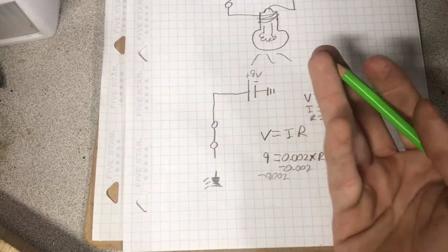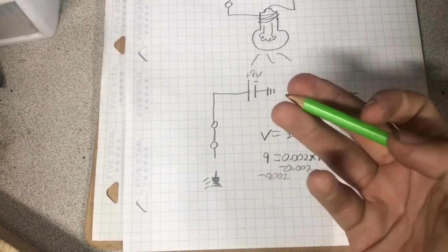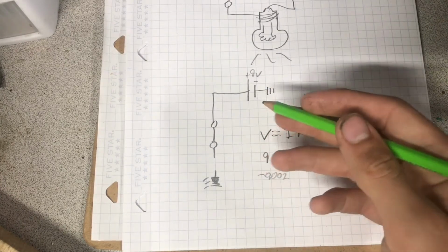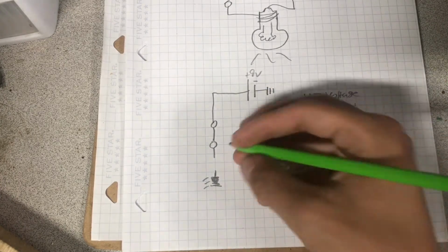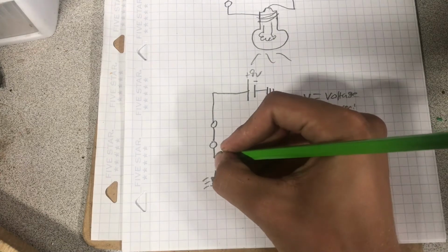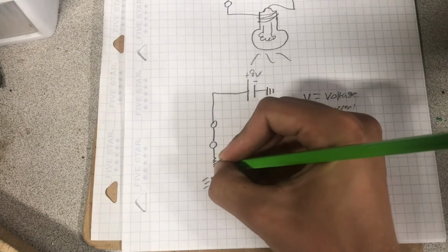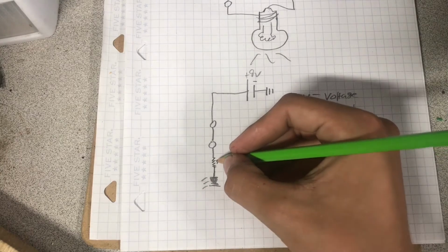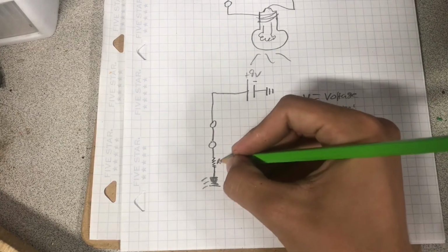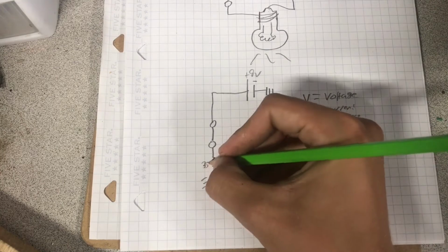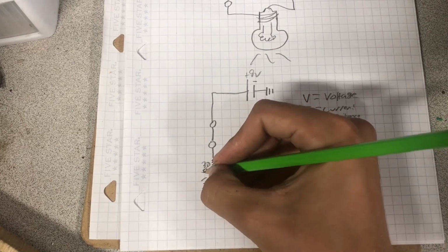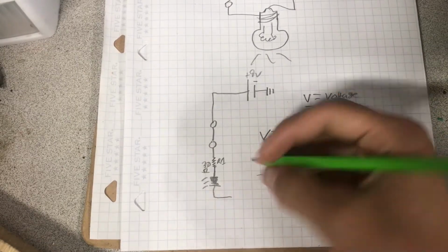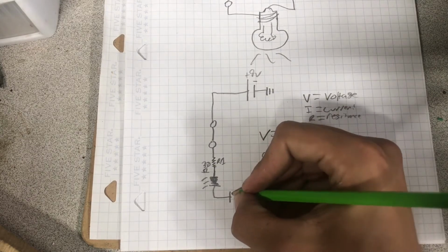If you can't find a 350 ohm resistor, then sometimes you might be able to substitute something a little bit higher or a little bit lower. It's okay. If you do something a little bit higher, it's not going to be as bright, but sometimes that's not going to matter. If this is just like a power indicator light, it's not going to matter. So we'll have R1, 350 ohms. There, that's going through our LED. This gets bled off to ground.